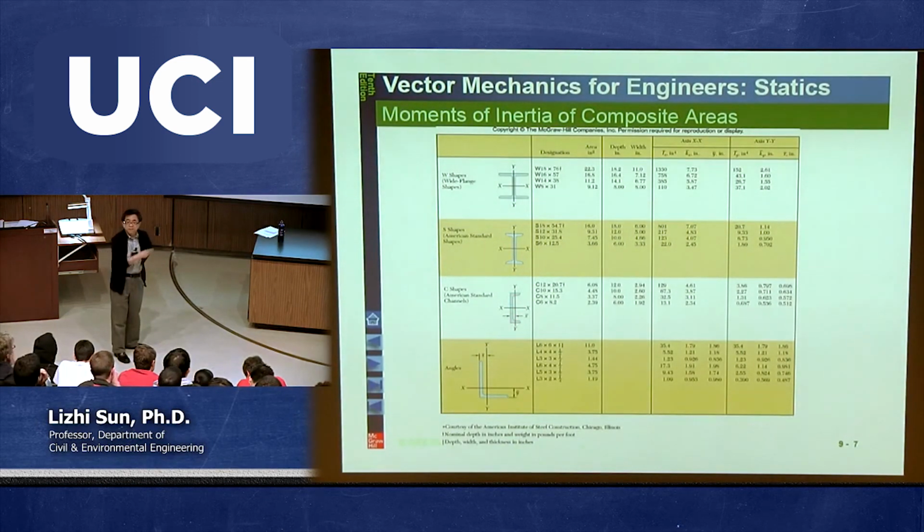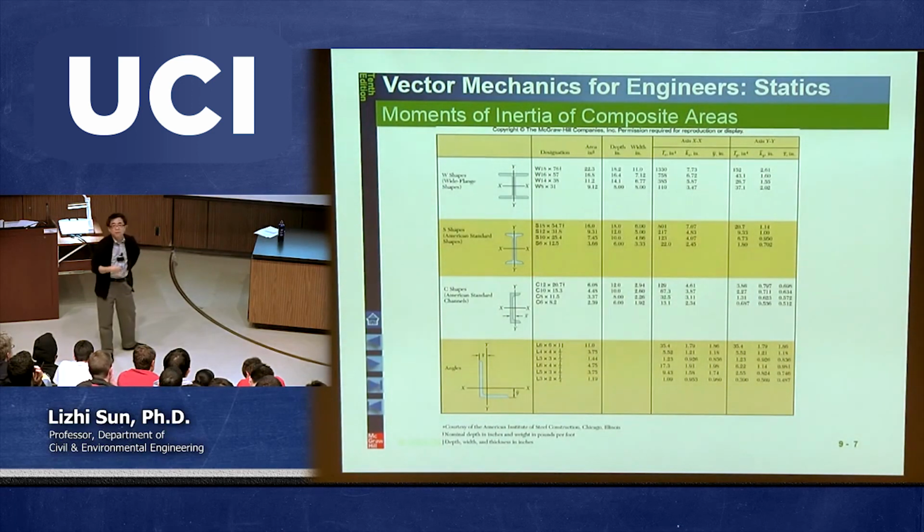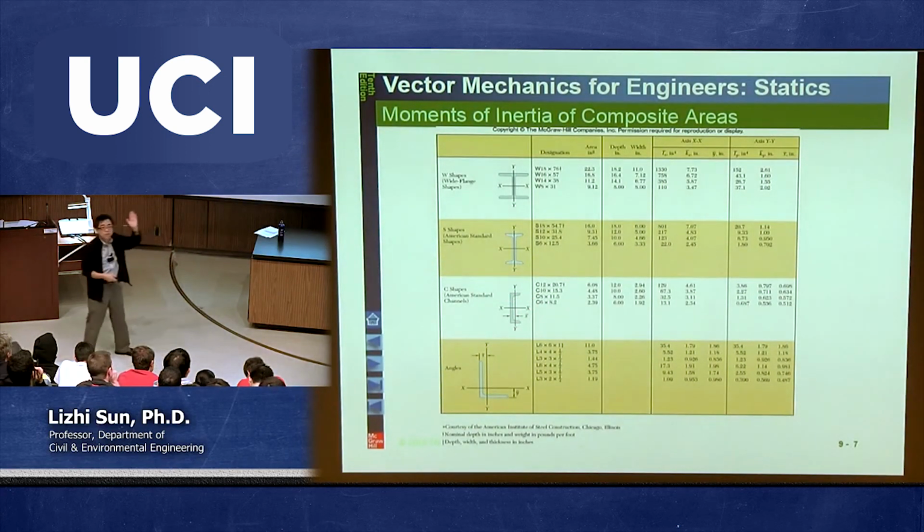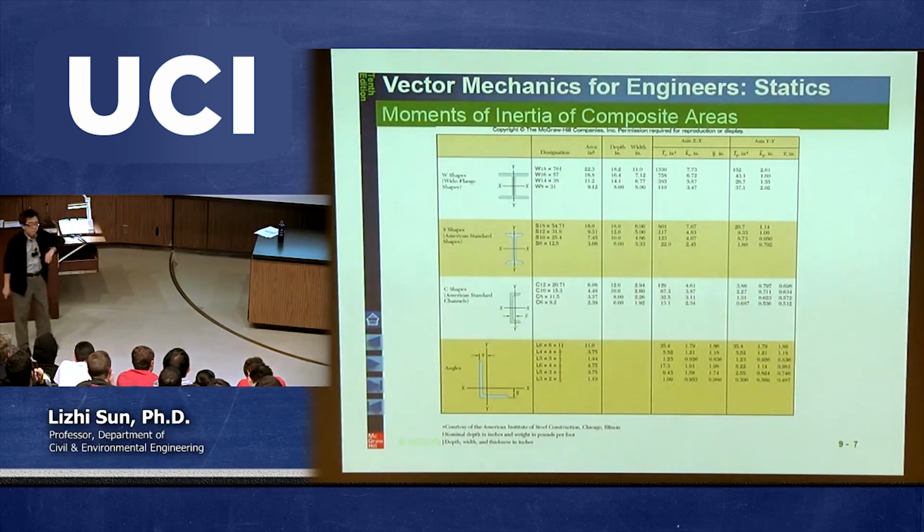Same thing. Okay, but the geometries can be different. The bottom line is, from this one, you should be able to calculate the moment of inertia with given both x-axis or y-axis. But if you want to calculate the moment of inertia with this y-axis this time, then you do need to use the parallel axis theorem at that time.